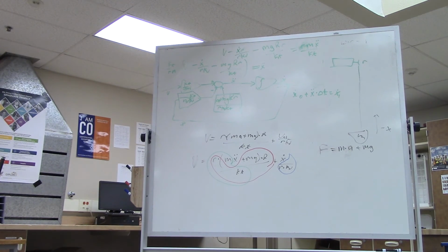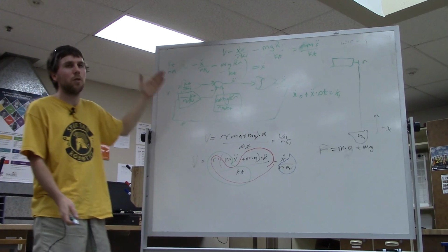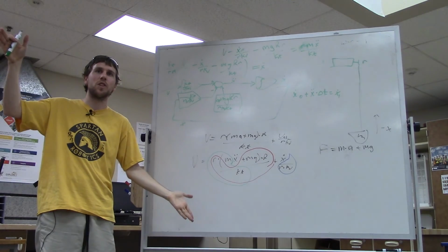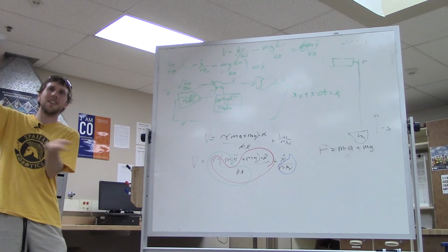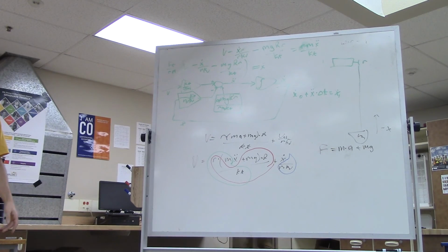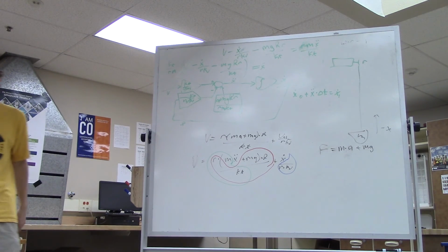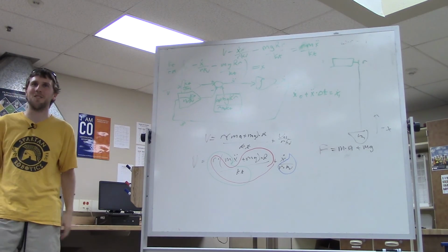Yeah, so why not just figure out what your voltage should be and just apply that every loop? Because the system changes, right? It doesn't actually act this way. It acts close, and so you'll diverge over time. So that's where control loops come in. If our model says if we apply, say, 12 volts for 3 seconds, we'll move the right distance and decelerate to a stop perfectly. But we know in robotics that's never true. If you just turn it on for 3 seconds, it's going to be close. So that's where the controls come in, where you're trying to correct for where your model doesn't match. Now, if we had a perfect model, we could just apply the correct signal, and we'd work. But that's not how real life tends to work.